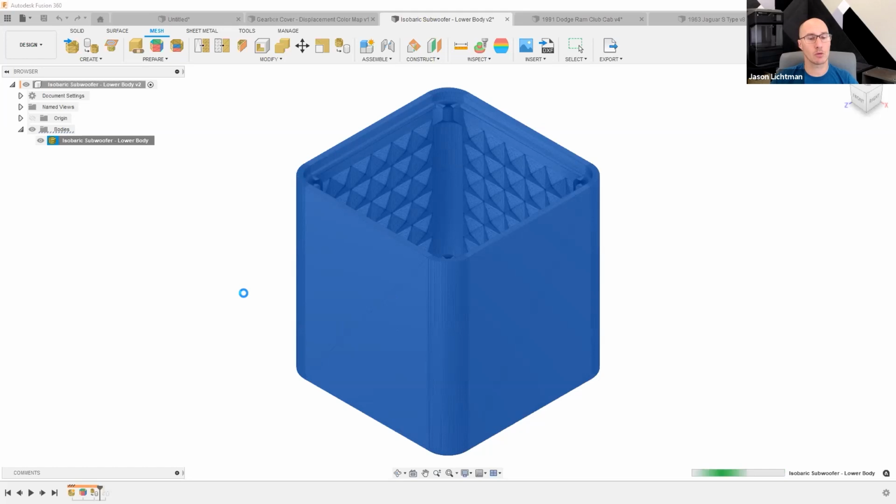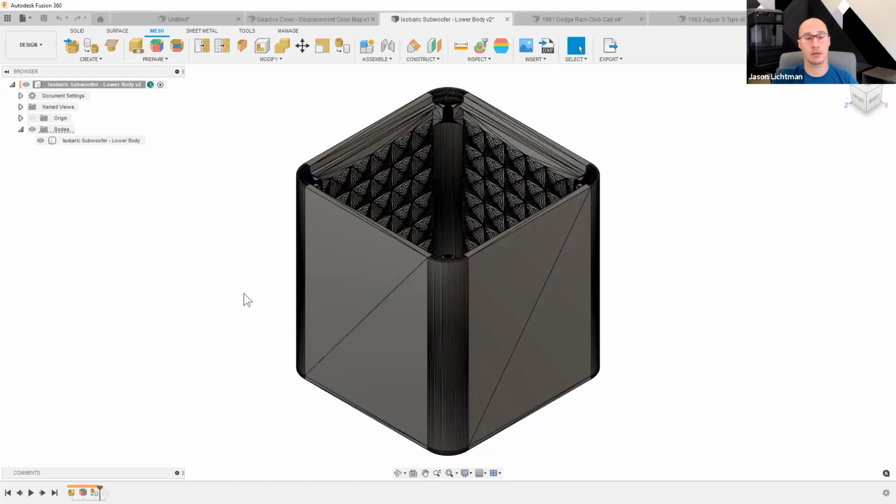It's going to take about probably 10 more seconds or so. It'll complete, and then we'll go and take a look at this. And I'll show you that you can clean this up pretty easily in Fusion 360 as well. So once it's clean like this, it actually still looks like the mesh did, but the edges are a little bit bolder. I can select a triangle that represents a flat face, and I could hit the delete key on my keyboard and it will find other faces that are also flat within a tolerance and clean it up.